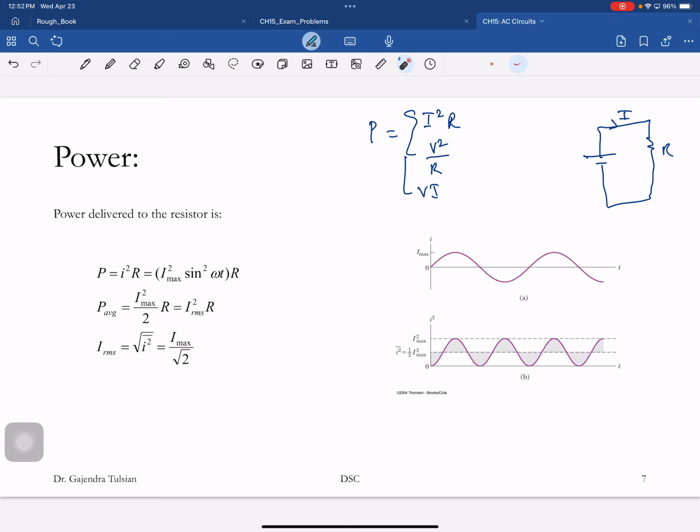So look at this. Let me turn this light on. If this light turned on, it's being fed by an AC signal, and look at this. That's one cycle. You have 60 of those. This is the brightness of the bulb. The bulb is blinking on and off 120 times a second.